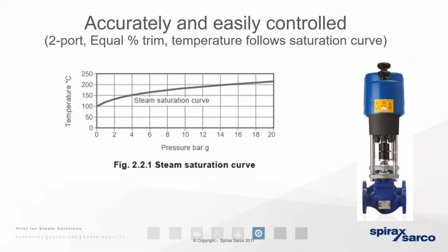And because condensate has got the same pressure to temperature relationship, the condensate that is going to exist in the distribution steam pipe, where we're distributing the steam at that nice high pressure, will exist as a liquid at 184 degrees. But if we've reduced the pressure of the steam at the process down to 2 bar gauge, we know the steam and the condensate will exist at that point at 132 degrees. So it really demonstrates that by manipulating the pressure, we're actually controlling the temperature.